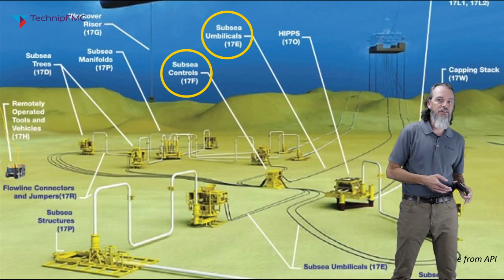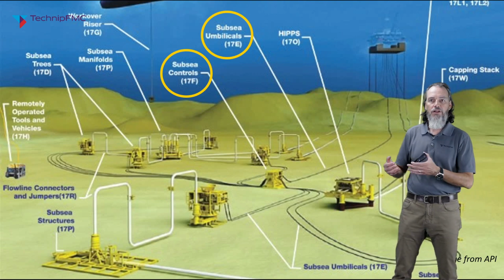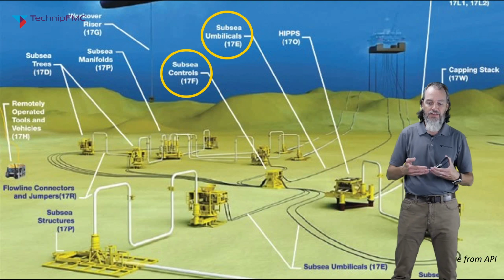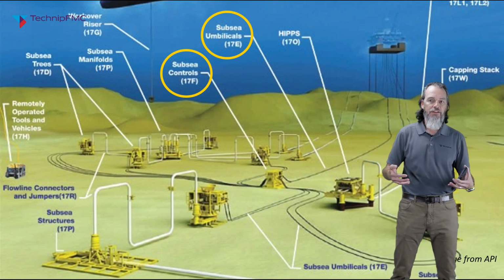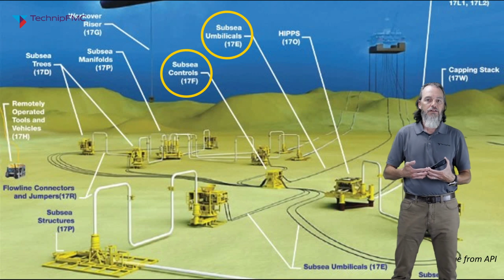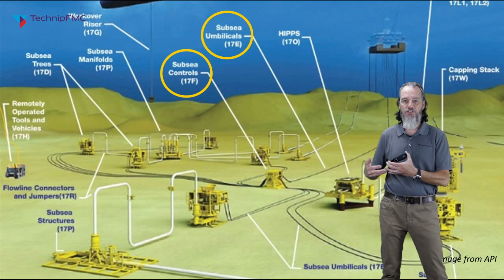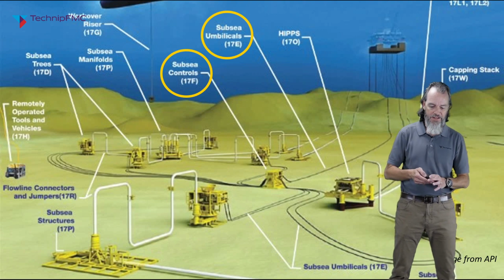Control tubing is defined by the outer diameter, but umbilical tubing is defined by the inner diameter. Understanding this interface is critical so that when a piece of tubing is procured, they match appropriately. So understanding how the material is defined is super critical to make sure the interface is intact.